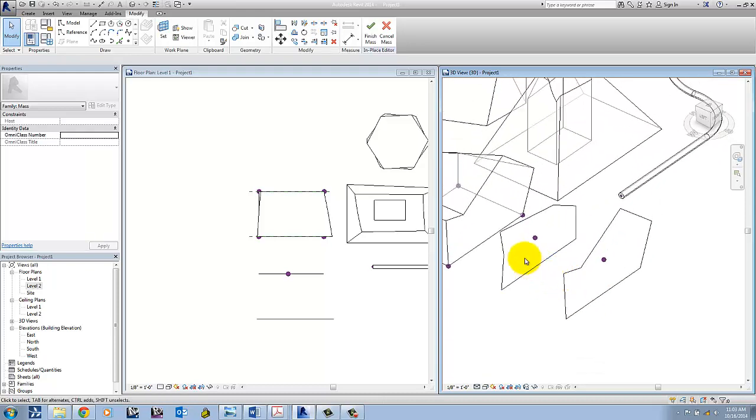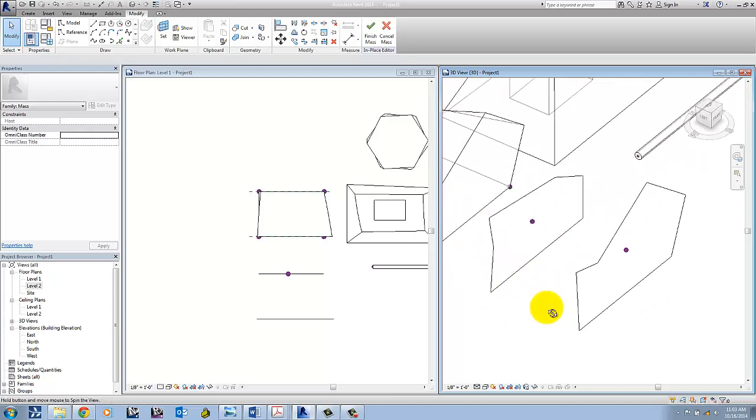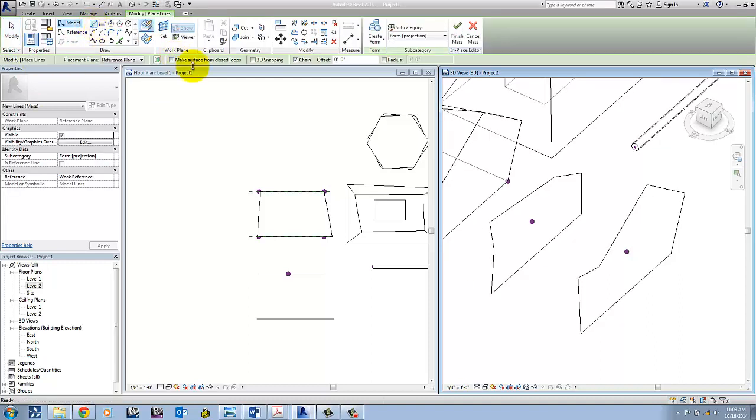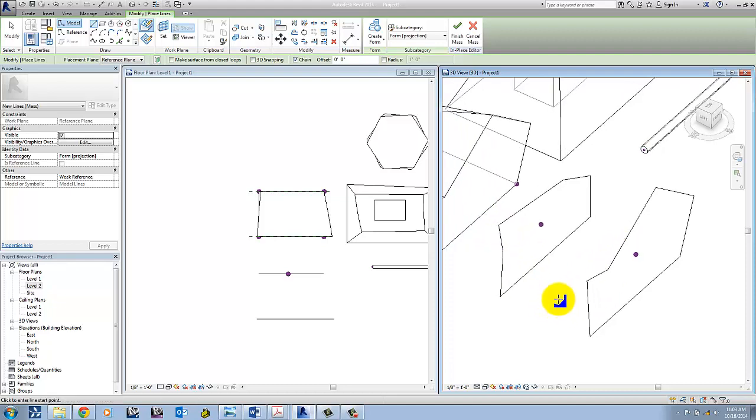All right, so say the way that it did this end, we didn't really like it. We want to manually create each of those surfaces. We can do that through just creating lines and using a tool called 3D snapping. So if we go to lines, what I essentially want to do is connect the points that I want it to connect to.